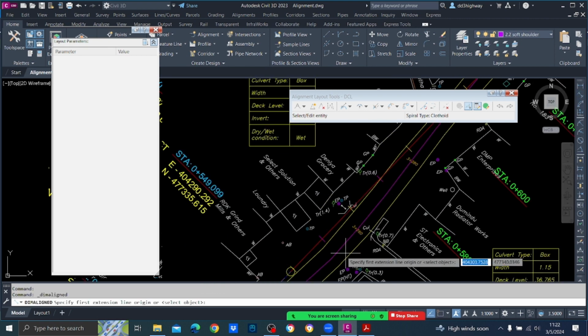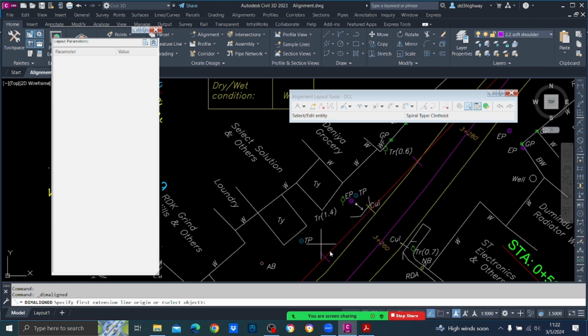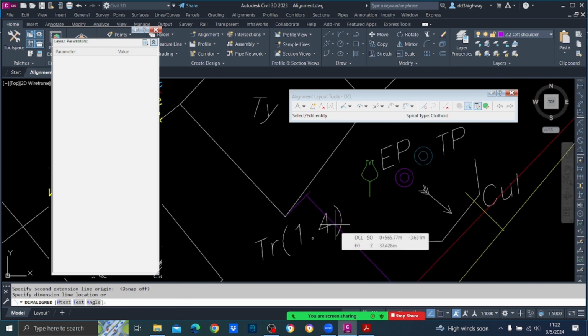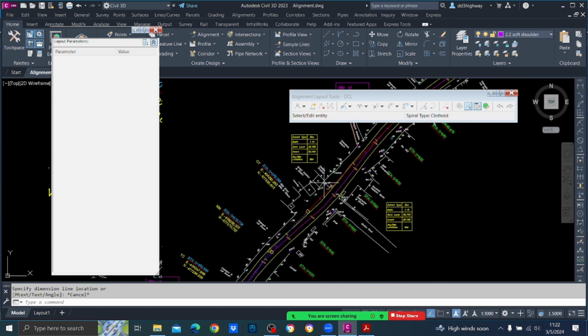We see the difference from this point. Our road is, say, 3.5 lane width, 1.5 hard shoulder width, that is 5, 2 meters off shoulder width, that is 7, and 0.6 drain, so that is 7.6. So we'll see whether you are having 7.6 here, from here to here. It is 5.1. So that is 7.3, meaning you want some 2 meters acquiring from this place.